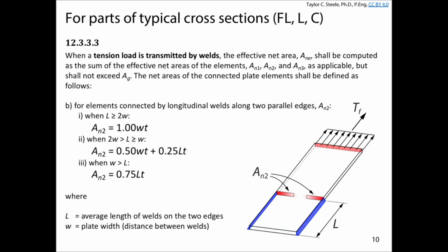It's quite common to not weld the end of the tension member and just use 2 longitudinal welds instead. And that's perfectly fine, and it's common practice. The welds are actually probably the best way to do your welding, but that has some implications on how much of the cross-section at the ends of the welds is going to be effective in carrying that tensile stress. As you might expect, it's proportional to the length. If you've got really short welds, like if you only have welds something like this and like this, there's not very much space for those welds to transfer the stress into the tension member, and so the net effective area associated with really short welds tends to be quite small.